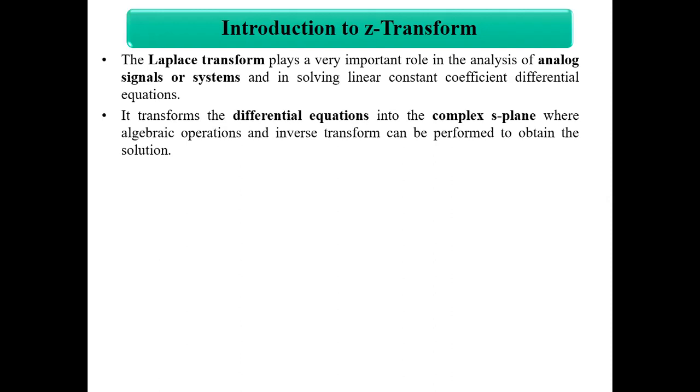We convert that signal or system from time domain to frequency domain, and for that Laplace transform is used. Now all the continuous time systems or analog systems or signals are actually represented with the differential equations. So these differential equations are transformed to the complex S plane by using the Laplace transform, so that we can get the frequency analysis of the given system, which is represented by the differential equations.